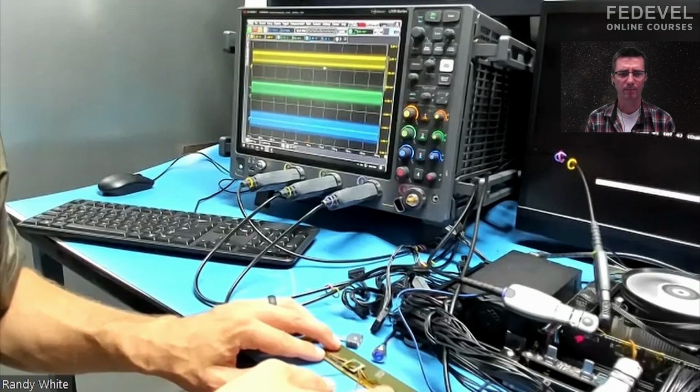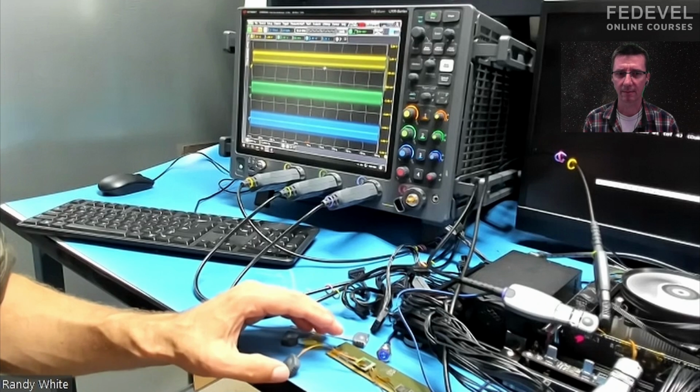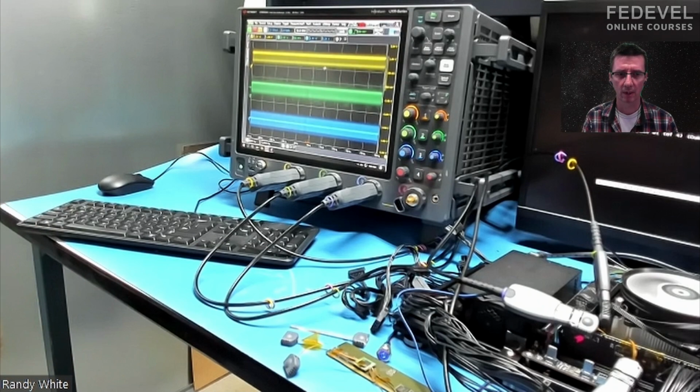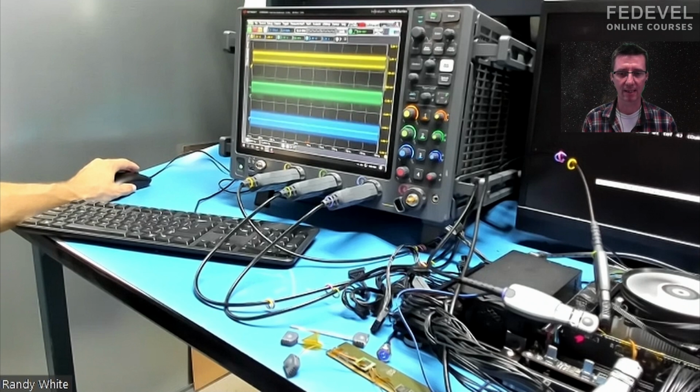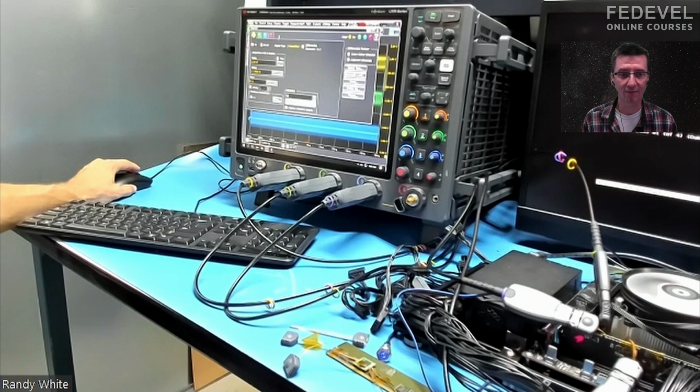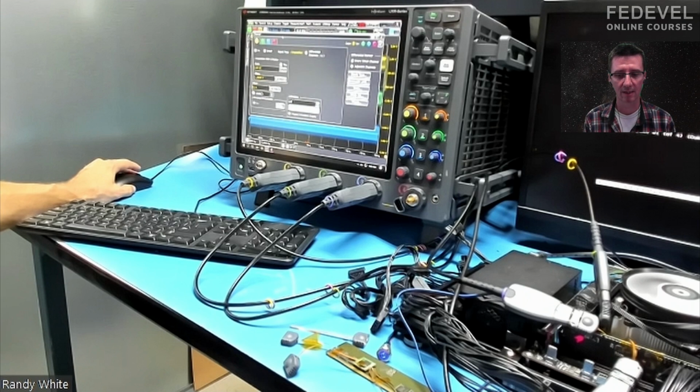Yeah, but I forgot the exact name, how it is done, but I think when you buy this kind of interposer, you also can download the S parameter files or something, and in these very expensive scopes, you can actually virtually probe exactly the signal on the memory chip and see it, because if you have this S parameter model, you can eliminate all these effects from the interposer and connected probes. Or am I wrong? You are absolutely correct.